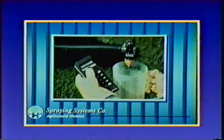In addition to nozzle type, the size or capacity of the orifice can influence the droplet size. The larger the orifice, the larger the droplet. Remember, when changing to a larger capacity nozzle, applicators should calibrate and mix accordingly. A few minutes spent choosing nozzles can help prevent possible spray drift or poor pest control, but controlling drift doesn't stop at selecting the correct nozzle. The sprayer operator has other options to ensure drift is kept to a minimum.